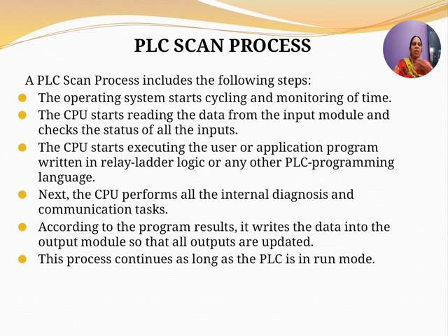So what is the logic in the PLC scanning? The PLC program is executed as a part of a repetitive process which is referred to as scan. A PLC scan starts with the CPU reading the status of the inputs. The application program is executed using the status of the inputs. Once the program is completed, the CPU performs internal diagnostic and communication tasks. The scan cycle ends by updating the outputs. So this cycle repeats continuously. The cycle time depends upon the size of the program, the number of input-output sections and the amount of communication required.